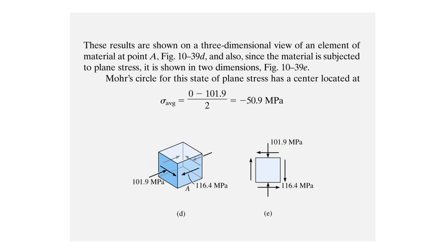Now we take a stress element at the top, at A, because that is where we have both the maximum shear and the axial loading, except that bending will give you compression. For ductile material it doesn't matter, because the yield stress under tension and compression is the same.